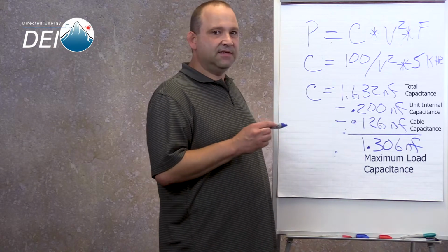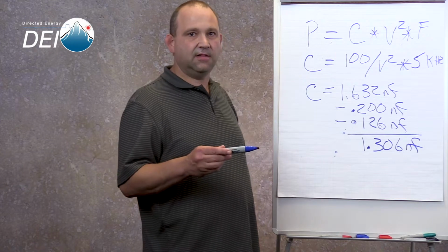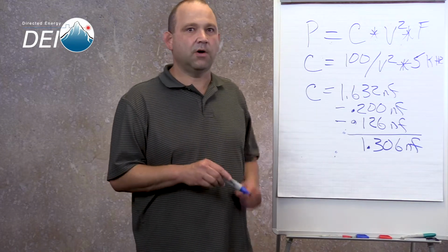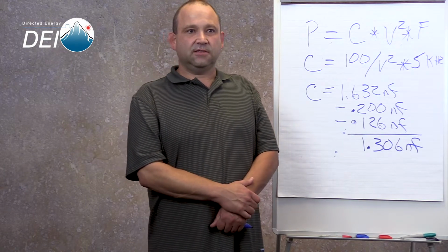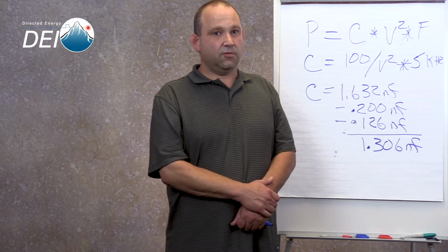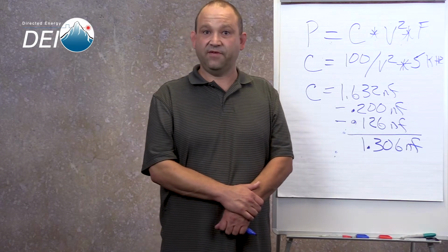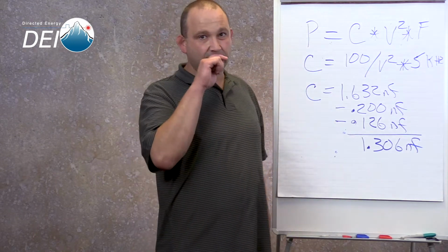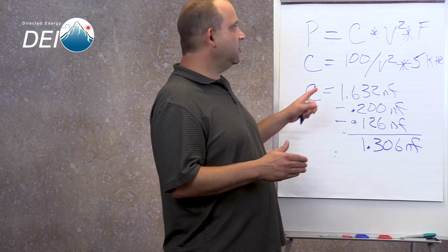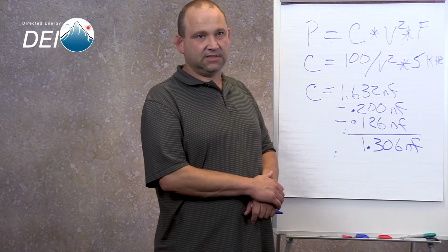Now you can apply this to each one of our other units, our PVX-4110, our 10 kilovolt unit, which is 100 watts, our PVX-4130, which is a 6 kilovolt unit, which is 100 watts, and our PVX-4150, as I said before, is 150 watts. And you can use this formula and manipulate this formula any way you want. If you know your capacitance and know your frequency and you want to know what your voltage is, you can do the same thing.